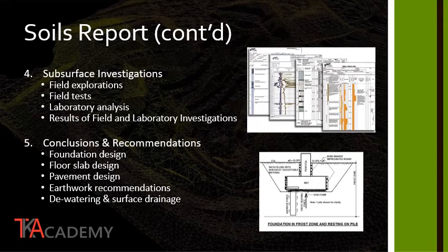The fifth part of the soils report is the conclusions and recommendations. This part of the report is the most pertinent to the design team. In this part of the report, the geotechnical engineer will provide the recommendations for certain systems such as foundation design, floor slab design, pavements, earthwork recommendations, and dewatering and surface drainage. Designers such as structural and civil engineers rely on this information to form the basis of their designs.